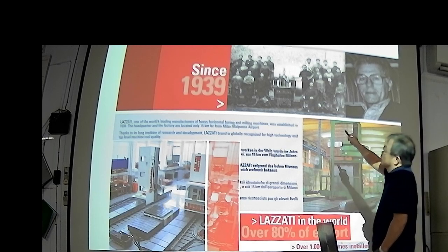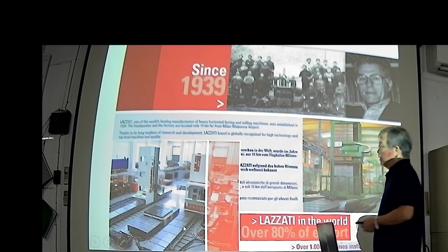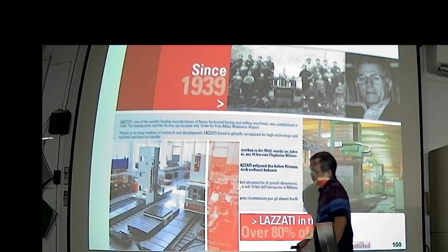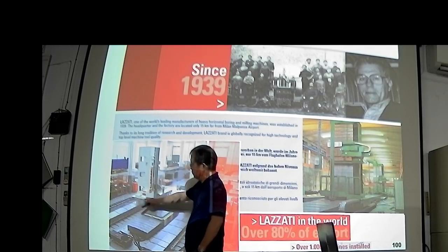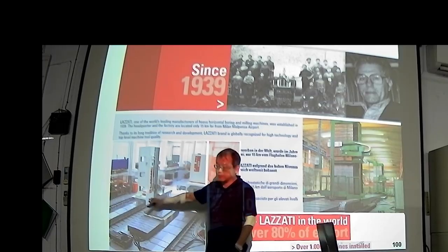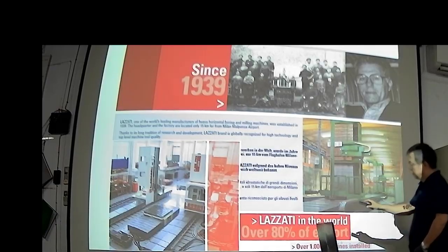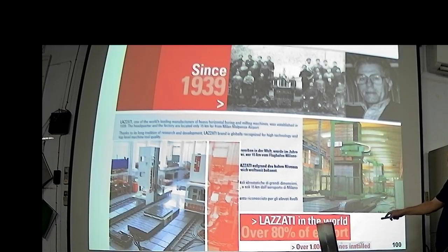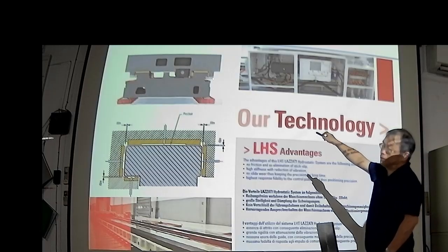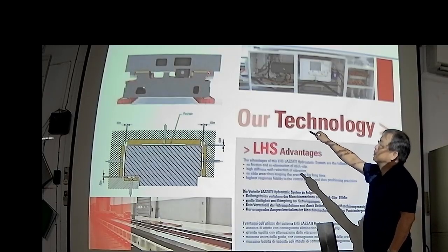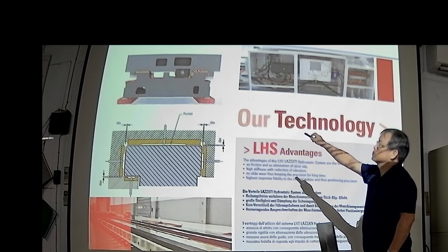So this is a floor type boring machine, from Italy. It's the same for the guideway system here. For the guideway system, this is a linear slide table. The guideway system here is also a hydrostatic bearing. This is a hydrostatic thrust bearing design. So you see here is a closed form guideway system. This one is closed form.